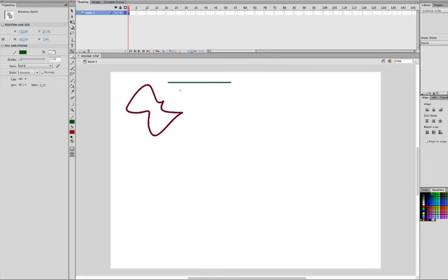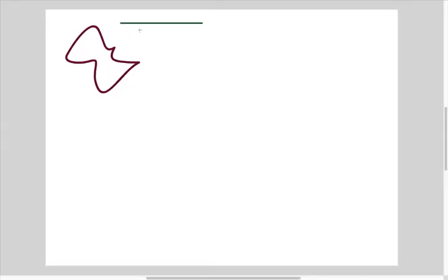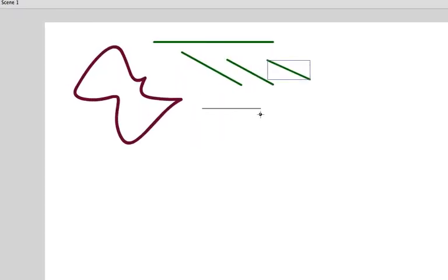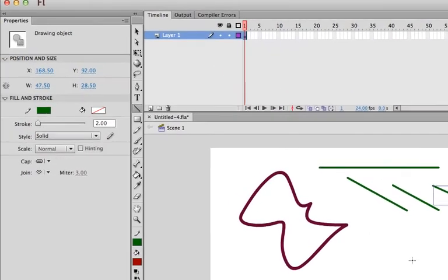Okay, line tool, constrain proportions just like other tools. You click and drag. You can change any angle you want. You can draw it at these angles, but you can snap it to 45 degrees by holding shift. Hold shift and draw, straight line, 45-degree angle, 90-degree, and you can go all the way around, whatever direction you want. So if you don't hold shift, you can put it anywhere. If you hold shift, you can constrain to 45-degree points. So that's the line tool, pretty basic.